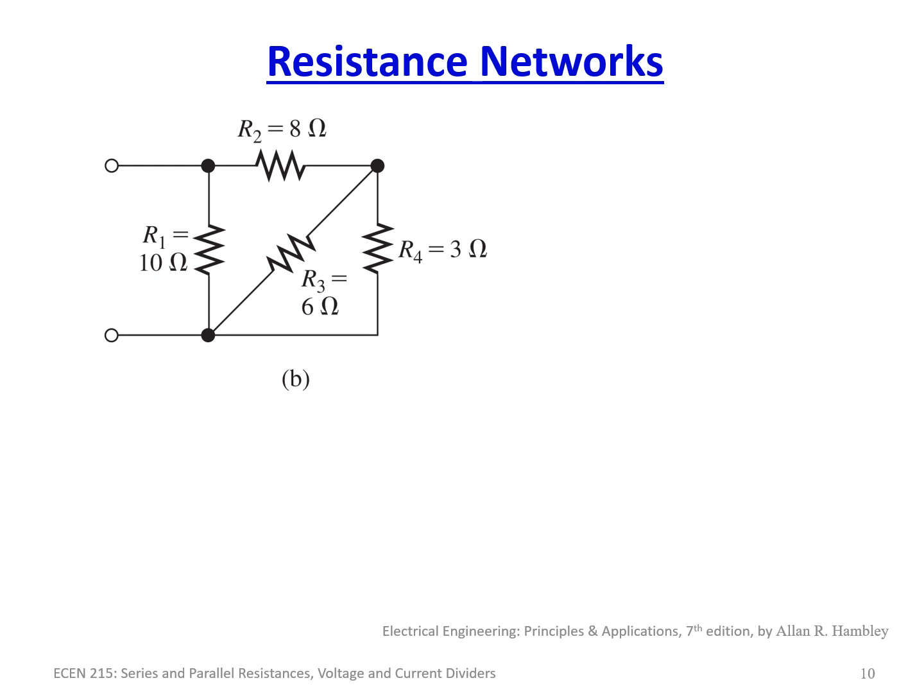Now, I will admit there is a circuit in the homework that's going to cause you maybe a little grief. It causes a few students a little bit of grief because it looks complicated, because it's a 3-dimensional figure, but honestly, it's not much more complicated than this. What you need to do is pay attention to what's truly in parallel and what is truly in series. And sometimes these problems where they have a diagonal, it's really meant to just make you think.